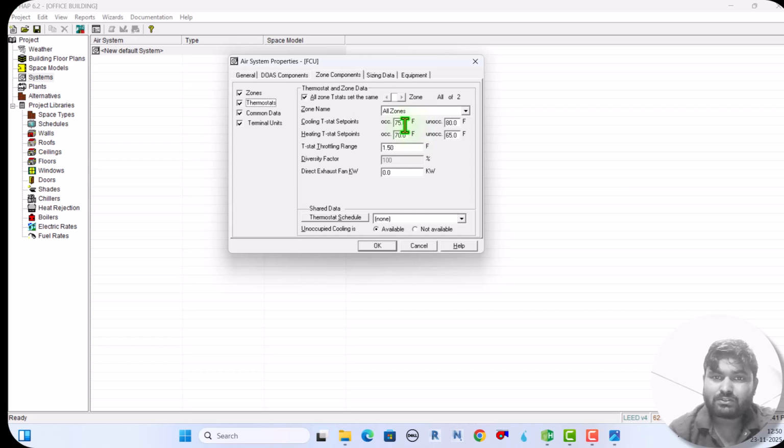Okay, so 75 to 80 on condition for our thermostat. Okay, same like the heating, but I'm not doing heating. This is an automatic default system and we can go. Okay, no need to change 74 or 80, it depends on the project, but it is the default system and it is okay. Here the thermostat schedule we have to create.